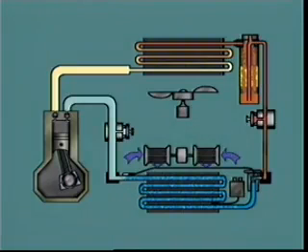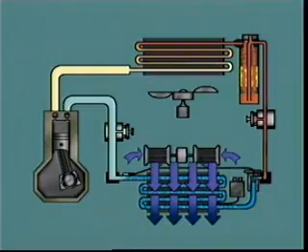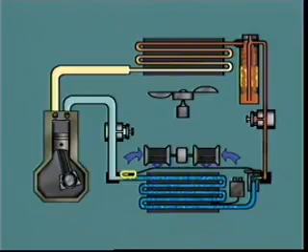The liquid expands into the larger volume of the evaporator, causing a reduction in its pressure, and this, together with heat from the air passing over the evaporator fins, causes it to vaporize. The temperature of the refrigerant leaving the evaporator is interpreted by the sensing bulb attached to the outlet.